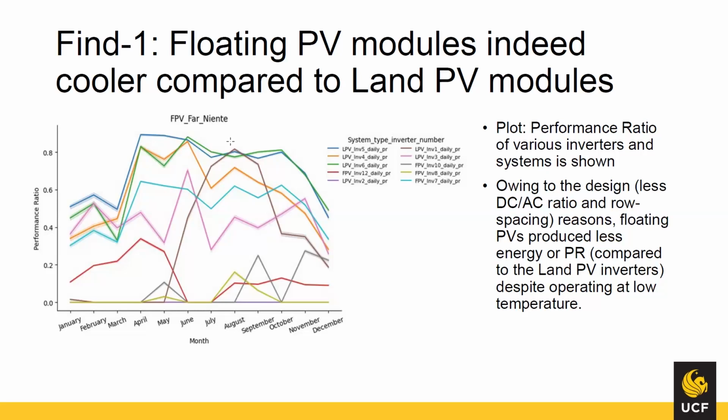But the issue is that we need the DC data, the DC power, or we can even work with the AC power data. The problem is that when the DC-AC ratio is more than 1, we are not collecting data in proportion to the sunlight, because it clips the power profile.